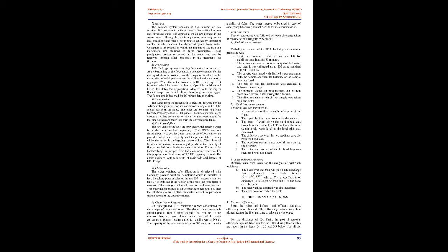The increase in the filtration rate may cause water to break through the filter material without treatment, while the sudden reduction in the rate may release a bubble of gas entrapped in the sand, causing it to make a hole through the filter bed. Other appurtenances include head loss indicators, meters for measuring the flow rate, and so on.